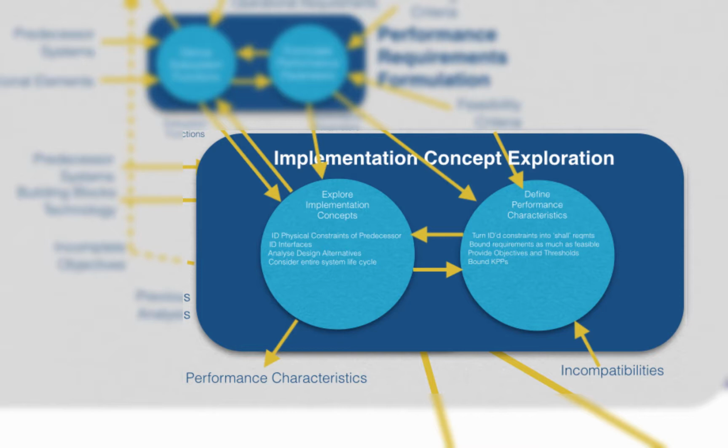For example, if we're replacing the reciprocating motor in a vehicle with a new hybrid half-reciprocating, half-electric motor, the vehicle's chassis and mounts, the fuel system, the drive system, etc. should continue to interface with our new upgraded motor. We're not planning on replacing any other major subsystems in the vehicle, only the motor. So we have to design our motor to adapt to the old motor's interfaces.